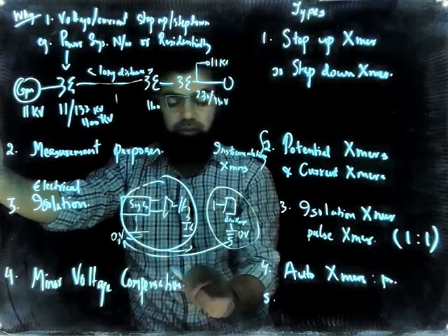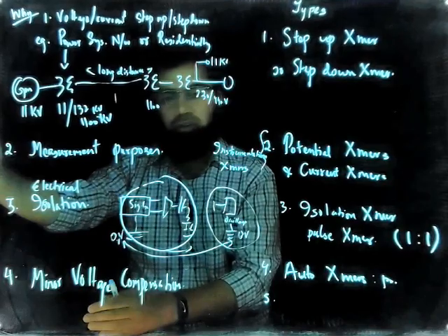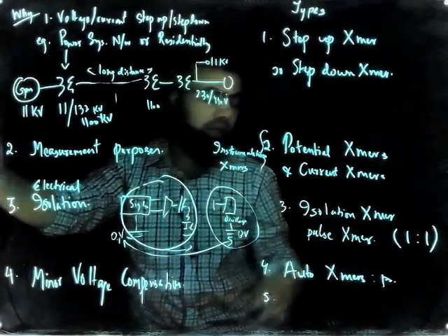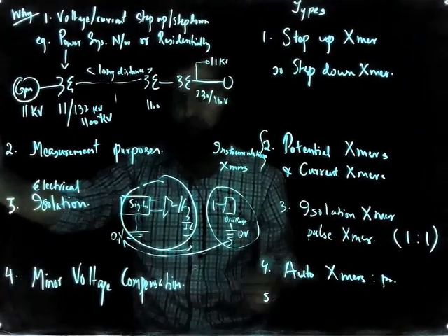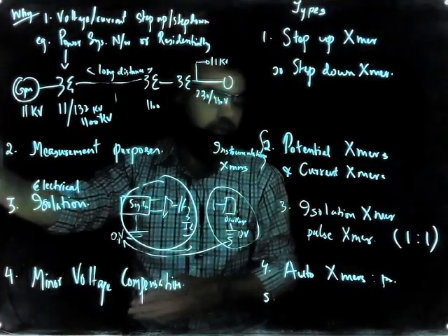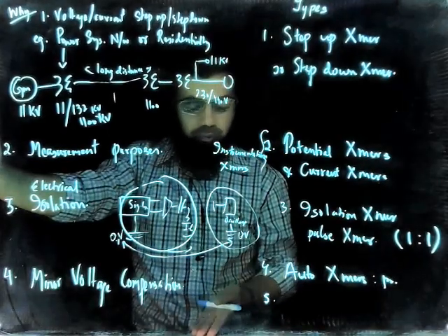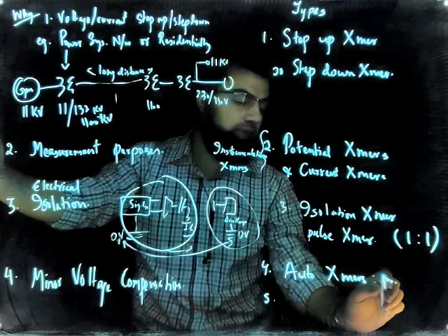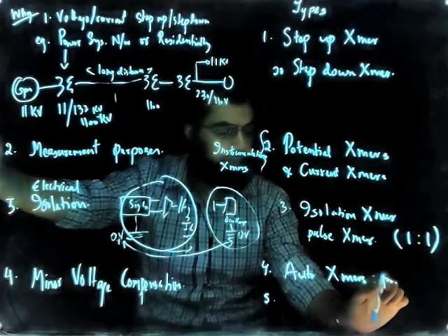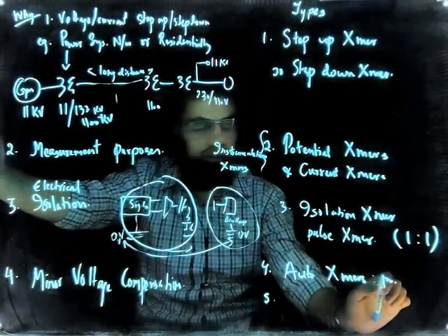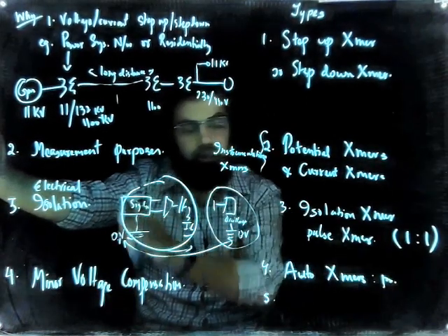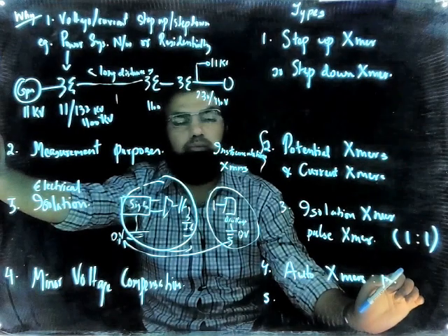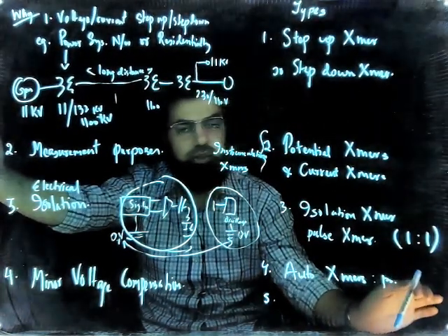What happens is that there may be devices where you require 230 volts, but you are getting 210, 220 volts. So there we actually use auto transformers. It does not have to do much of a job. It has to improve the voltage from 200 to 230 volts. But the fact here is that, as compared to the normal transformer, the power rating of this device is very high. We will be actually studying that.